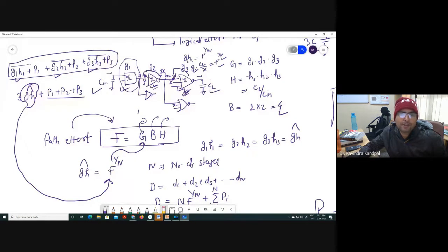After finding Y, you want to cross check whether you have made any mistake in the calculation. You can simply backtrack again, and this capacitance here should be equal to Cin. If it comes out equal to Cin, your calculation so far has been correct. So those who have calculated their answers, if they are able to backtrack rightly, their approach was good. Later on, they might have made mistakes while dividing the capacitances to NMOSes and PMOSes, but up to this point they will be correct. Understood this particular part?